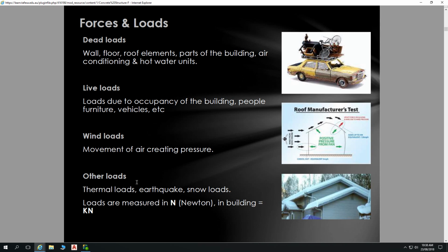You still need a crane up there. All the equipment that you would have had for that one day tilting up these slabs, you've got to bring back up there just for that one slab. So in some of the rectification work, stakes can be a little bit higher as well.